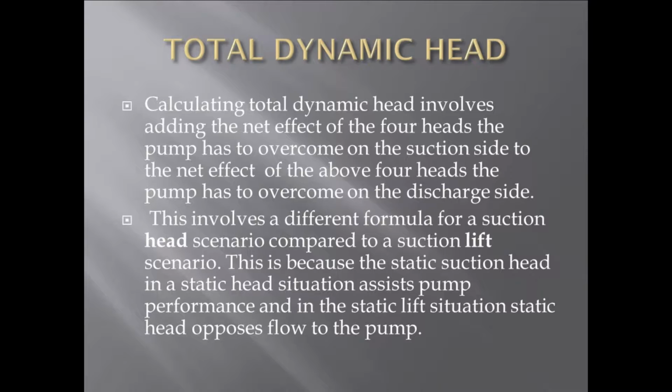This involves a different formula for a suction lift scenario compared to a suction head scenario. This is because static suction head in a static head situation assists pump performance, and in a static lift situation, static head opposes flow to the pump.